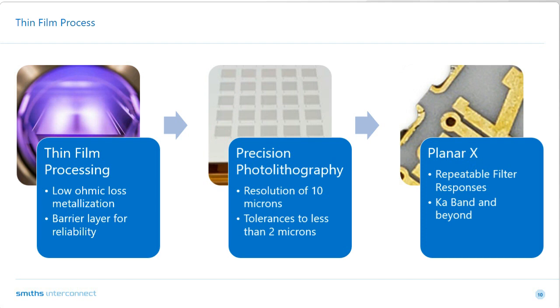Thin film provides a repeatable pattern by using high-precision photolithography to pattern a light-sensitive photoresist through a mask of the filter design. The typical process is laser pre-drill for creating the vias and edge wraps, a DC sputtering of the metals, the photolithography and etch, and finally the dicing of the substrate to the individual filters.